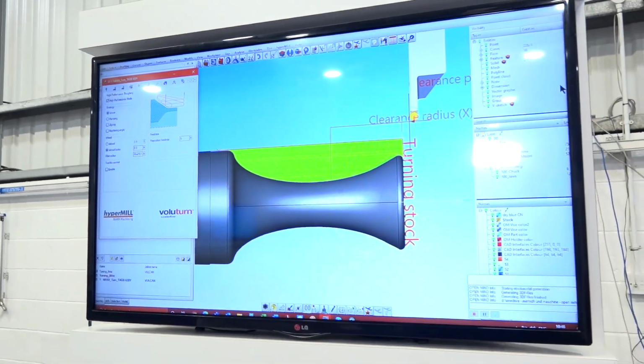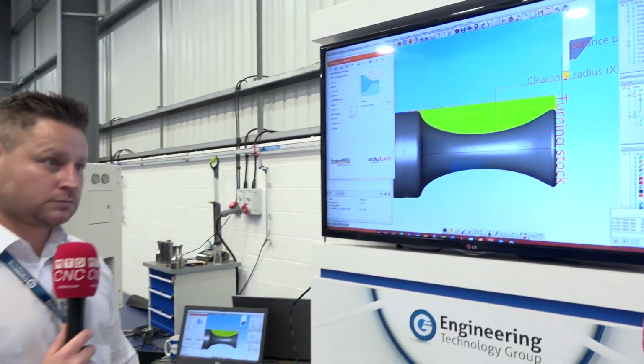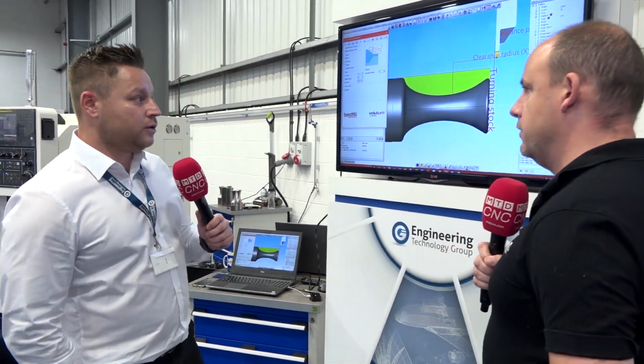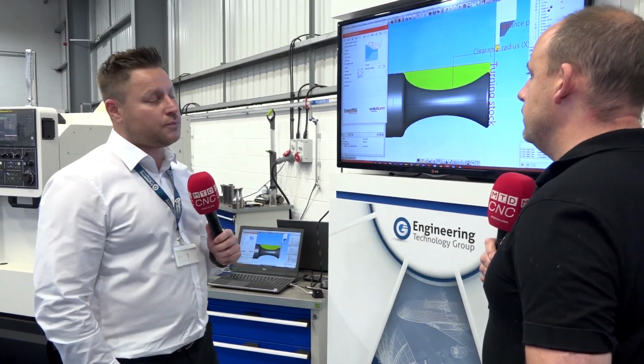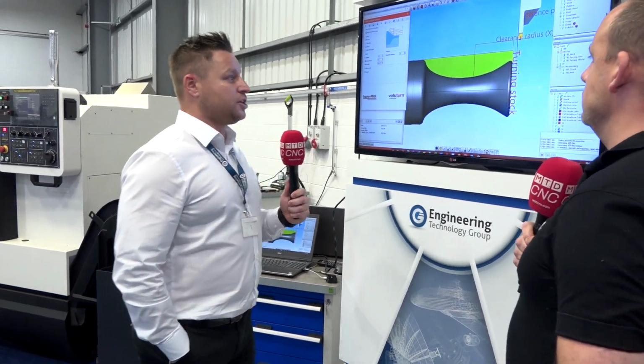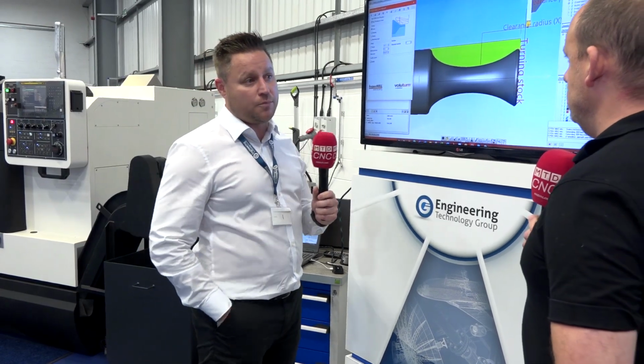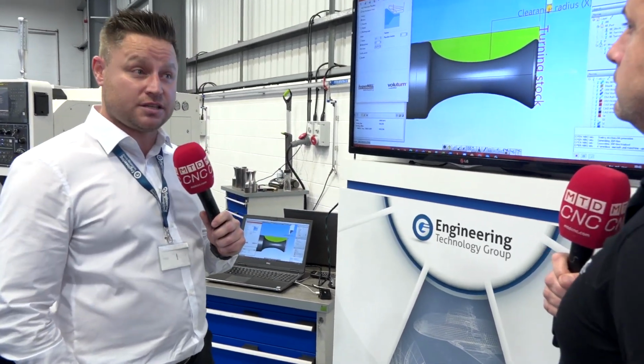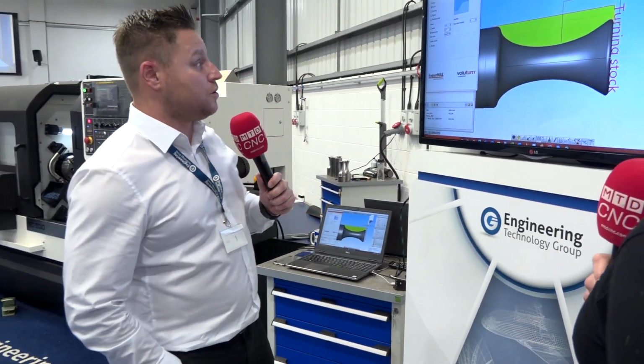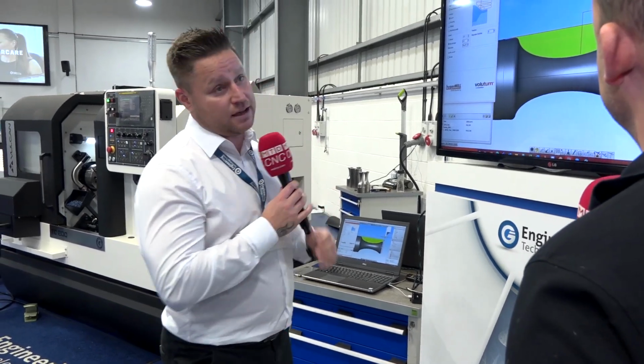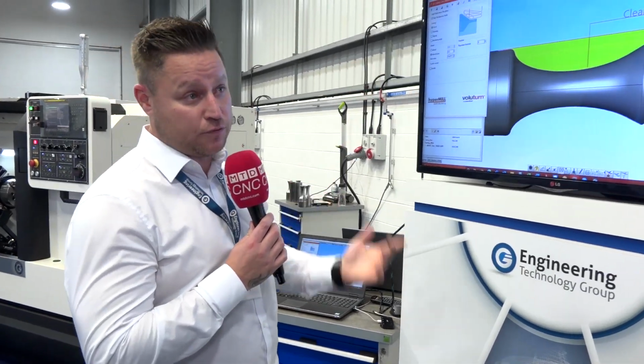Okay, and what about the actual speed of the process? So the speed the tool's moving, the speed of the spindle, what determines all that? How's that algorithm worked out, if that's what it is? Yeah, we've got a formula that we use, that we always use the VC that's provided from the tooling supplier. We have a general rule of thumb that we say 1.3 on the RPM, which is your G96 line. And then we also have the feed rate that's calculated in the background that we give a formula of 2.5 over the feed per revolution.